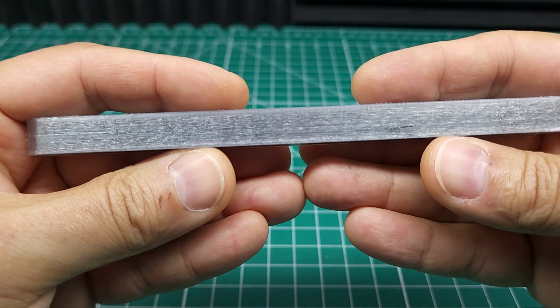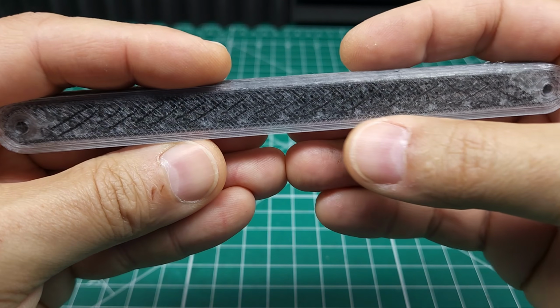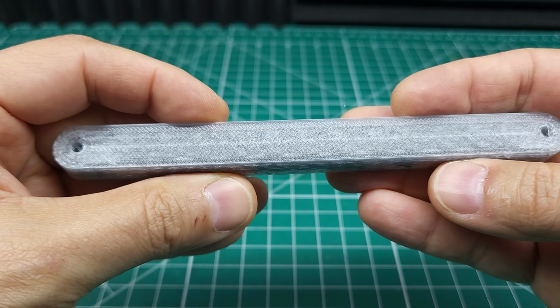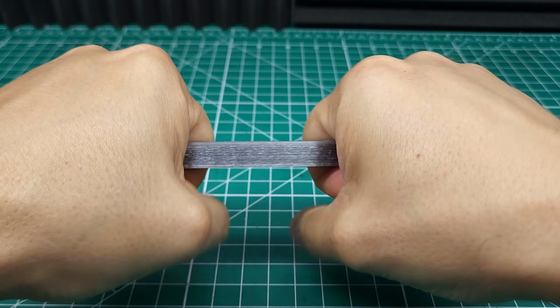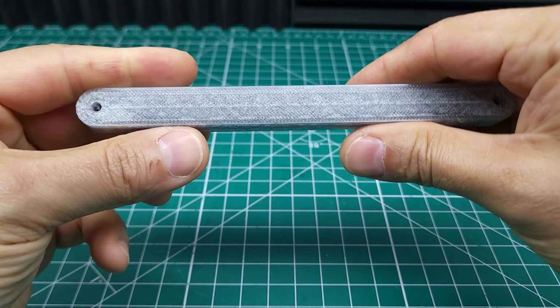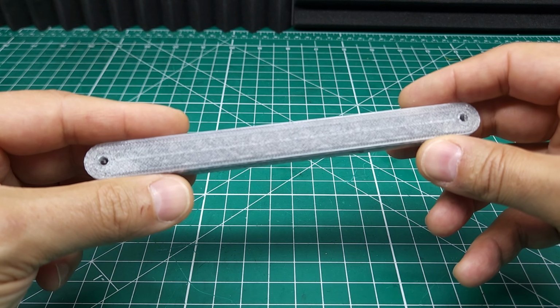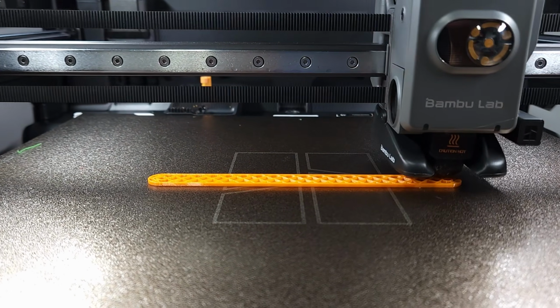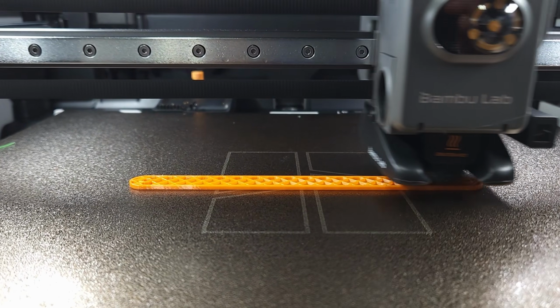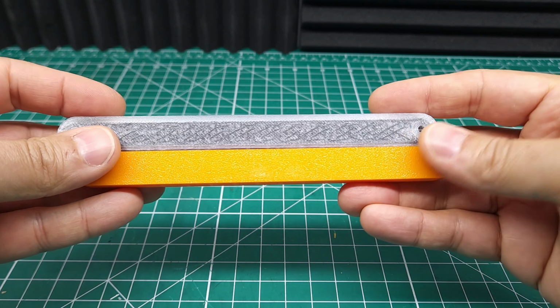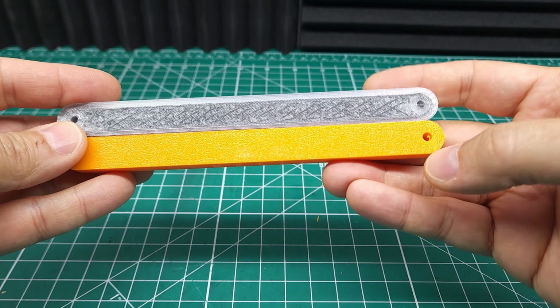And here's the final product. You can see the continuous carbon fiber hiding in there in the infill and all around the edge. And I have to say, especially for PETG, this is incredibly stiff. Let me print out a regular one in PETG on my Bambu Lab printer so we can compare how they feel. Obviously, this is going to print more quickly because it doesn't have that continuous carbon fiber in it. And by more quickly, I mean much more quickly. This took about 4 hours to print. This took about 13 minutes.